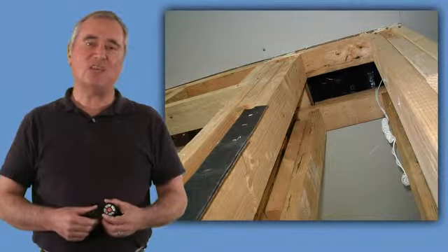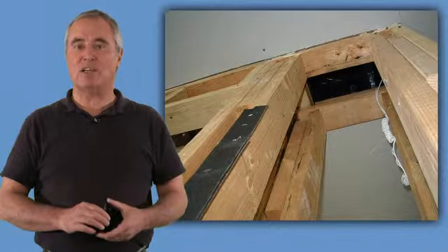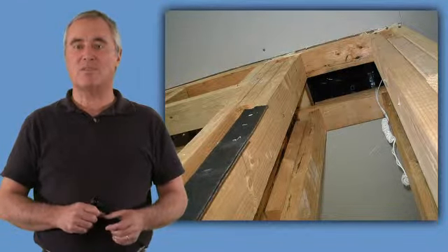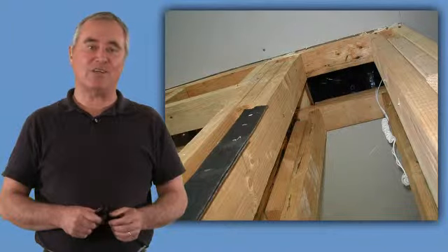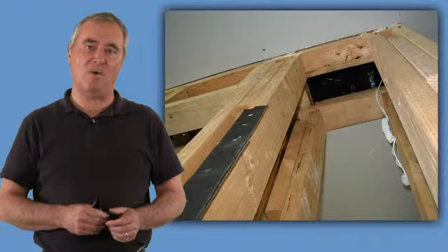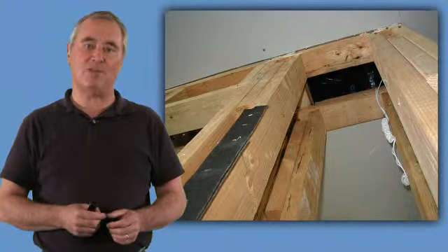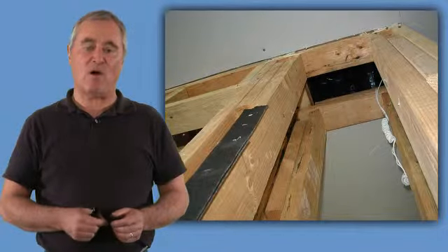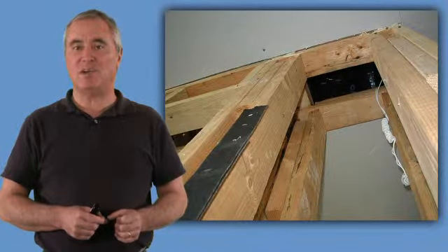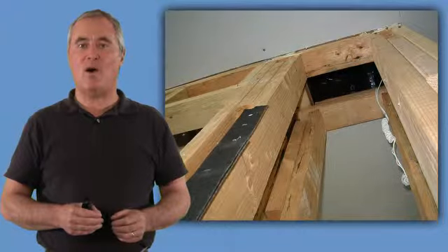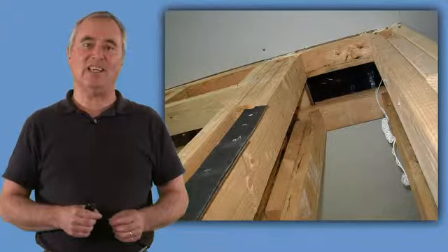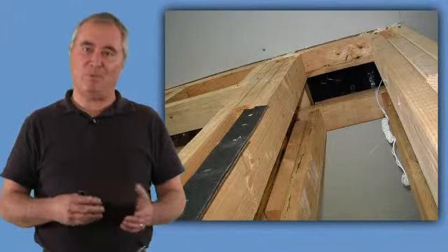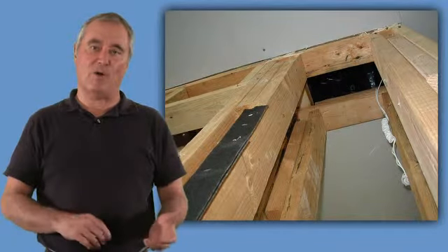One of the first things we do as we air seal is we look for the big holes. In architecturally complex buildings, we see many missing fire stops like this thick wall with an open wall cavity showing at the top. So our hierarchy for sealing leaks, we always want to seal big holes first before little holes.